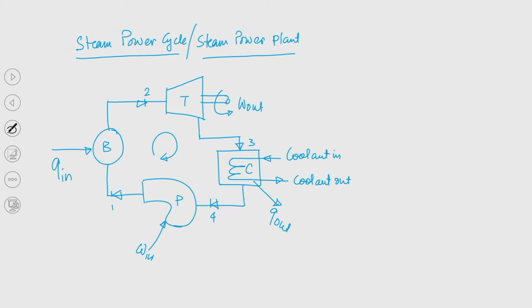Now, upon receiving, that means we are supplying heat energy, and at the cost of that heat energy we are getting work output, and that is why we need to calculate efficiency, right. We can understand that this part is there because we need to run this cycle in a cyclic manner, and as I said in the last class, the second law of thermodynamics puts a restriction that we should have a place wherein heat must be rejected, and that is why this condenser is there.